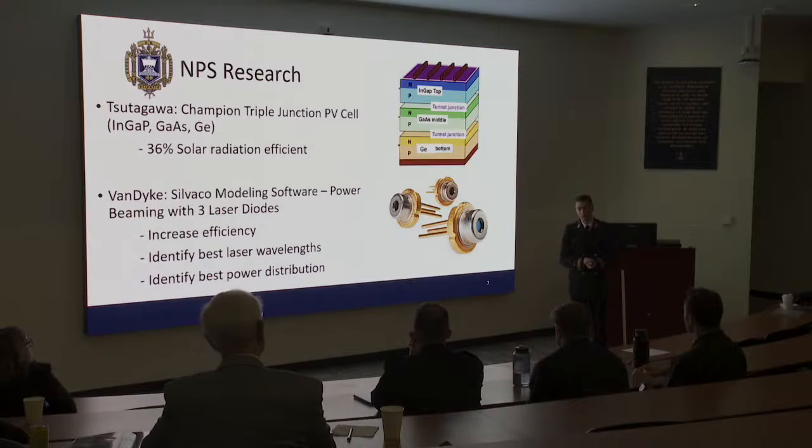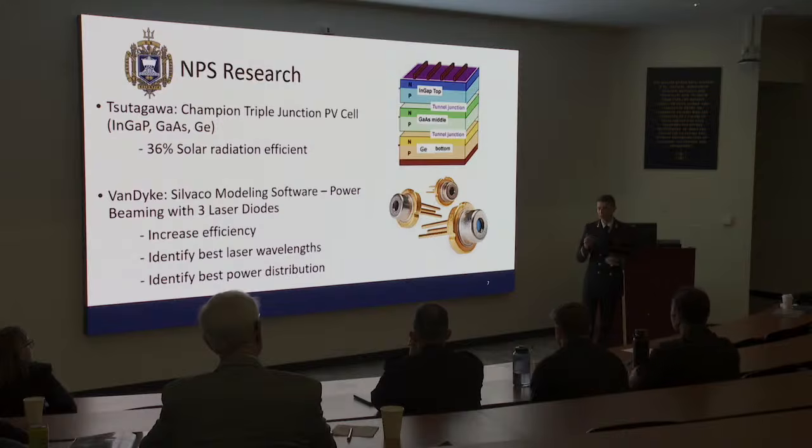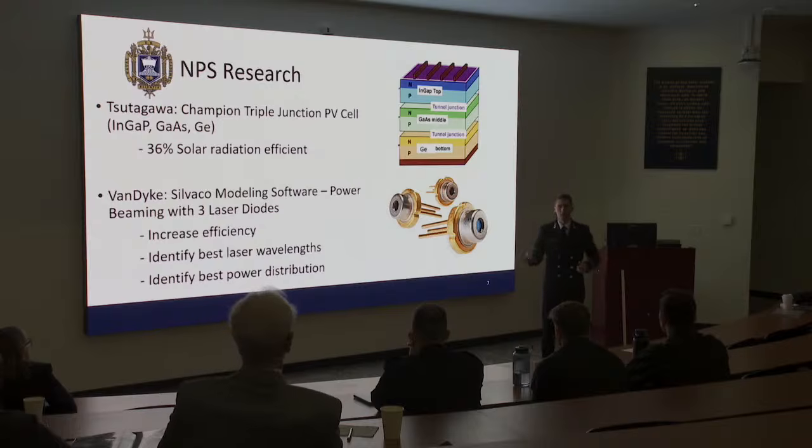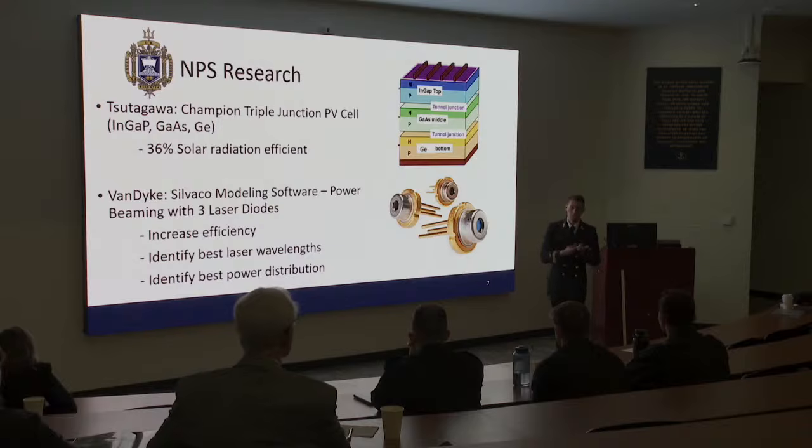Yes, sir, absolutely. For long-range power beaming, there are 2 primary methods: LPT, laser power transfer, and MPT, microwave power transfer. There are distinct advantages between the 2. The advantage of microwave power transfer is that, as you hit the nail on the head, the lasers that operate at these distinct wavelengths are attenuated by the atmosphere. That's why they're most applicable for space-based applications where we have no atmospheric attenuation. Microwave power transfer operates at wavelengths that the atmosphere doesn't attenuate, and it's a slightly more developed technology.